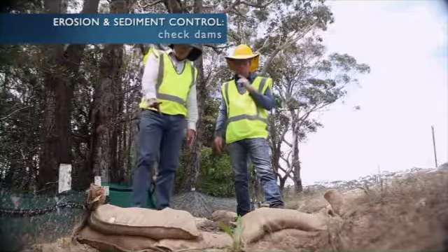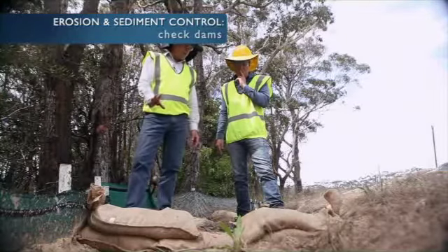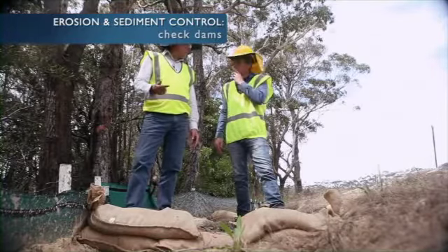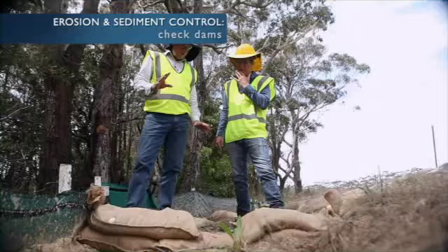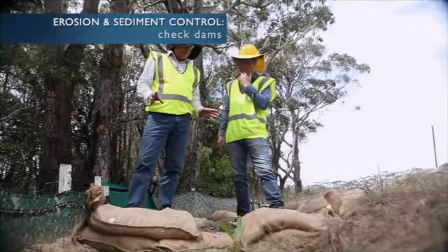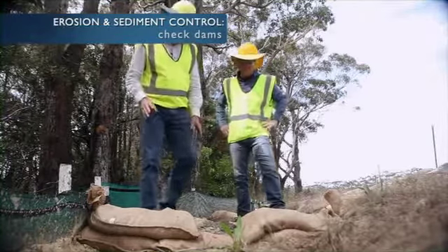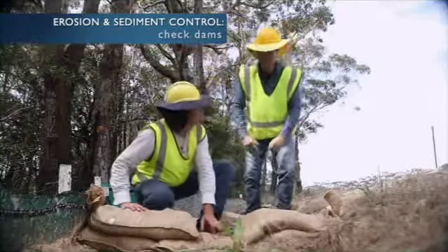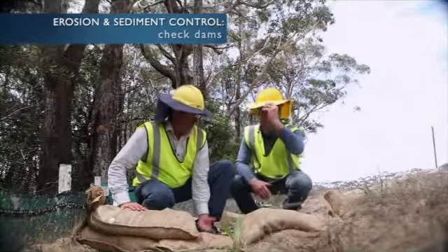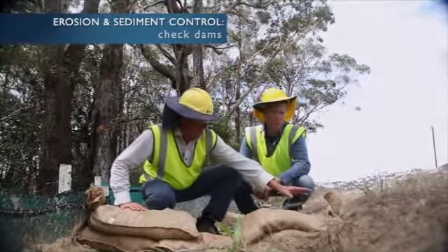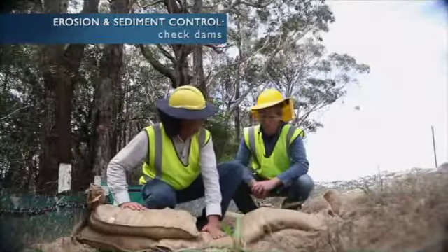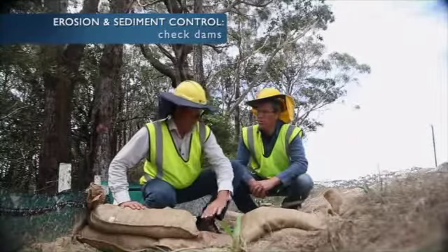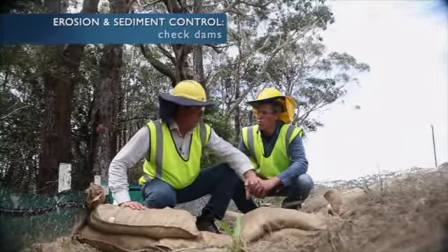Well, this one here is constructed of gravel bags. Generally, the check dams are constructed of gravel or sandbags or rock. Could also be geofabric wrapped rock. But a couple of important design considerations for them that you can see here. First thing, we want to make sure that there's a drop-down structure in the middle of the dam, so that'll allow the water to flow through, and to make sure that we've got the outside of the dam highly elevated above that drop-down. So that means that water's not going to flow around that dam and erode around the side.